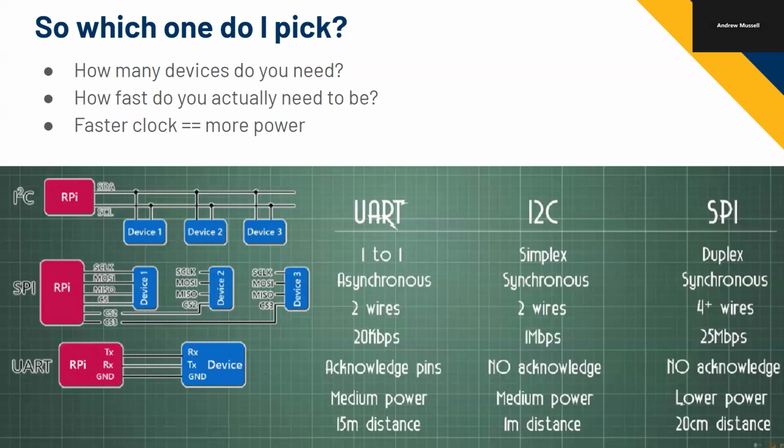It could also be that some ICs don't have I2C or SPI. Yeah, I mean, that's a very real engineering issue. Sometimes the chips that I want to do this function, the designers only give them a SPI bus or only give them an I2C bus. And usually that's for a reason. It's like, if you want to do this thing, you should probably use this type of bus, so we're only going to design the chip with this type of bus.